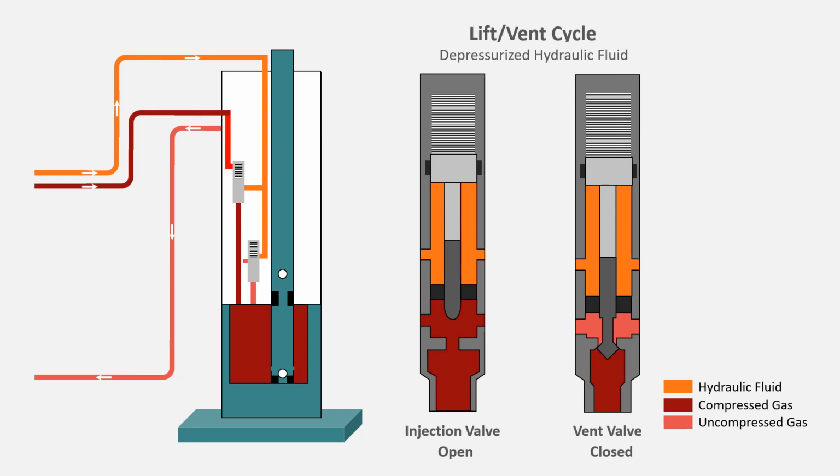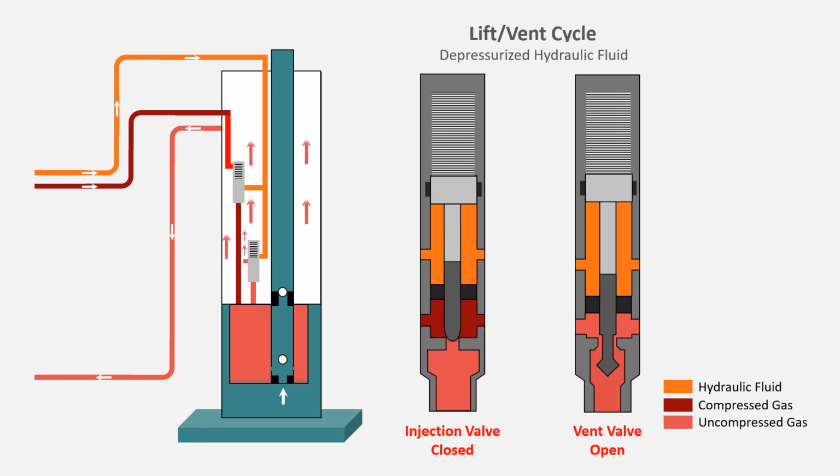At that point, the surface control skid reduces the pressure in the hydraulic pressure line, causing the chamber injection valve to close and the chamber vent valve to open. Without high pressure in the chamber, the tubing hydrostatic pressure closes the tubing entry standing valve, and the chamber standing valve opens as reservoir pressure drives production toward the pressure sink, causing the chamber to fill again for the next flush cycle. This pumping cycle continues for the life of the well.